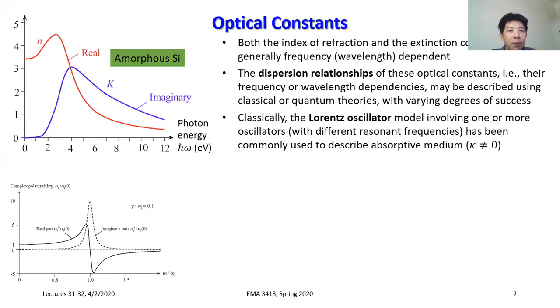Locally, silicon may still bond with 3, 4, or sometimes 5 neighboring atoms. So you have some local ordering, but no long-range ordering. So there's no periodicity. And oftentimes there's a lot of hydrogen inside to terminate some of the unbonded silicon electrons.